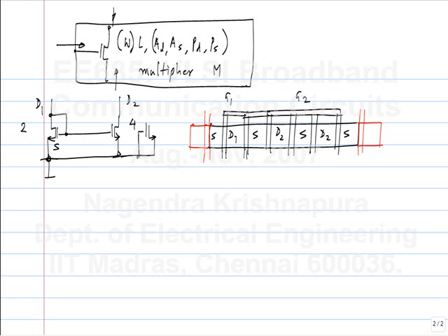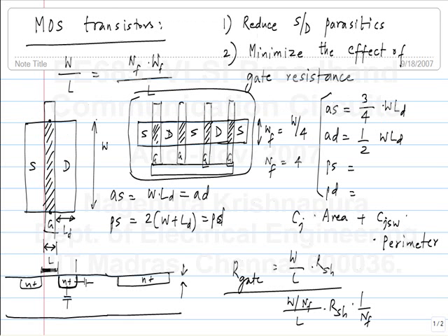So, you connect the gate also to ground, and you can connect the drain also to ground. So, no current will ever flow through this, and it's not connected to anything. But it will make sure that all these transistor fingers which are used in our circuit will have the same environment around it. Okay.